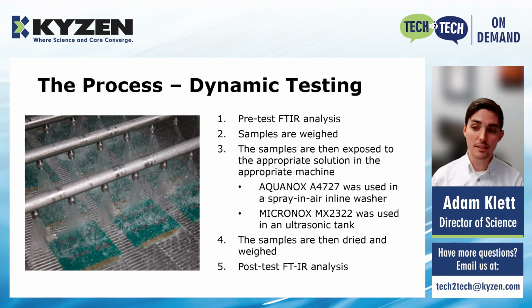And the Micronox MX2322 was used in an ultrasonic tank. In both of these cases, the samples were processed for 15 minutes, and then they're taken out, dried, weighed again, and then a post-test FTIR analysis was done to look at the change in the chemistry.